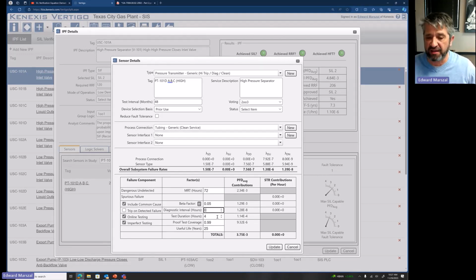So if you have a level transmitter, like a smart transmitter, it's running its program about once every 100 milliseconds to every 300 milliseconds. And so once every 300 milliseconds, it's going to run all of its diagnostic routines. So you need to basically understand for each component how the diagnostics are being performed and how frequently they are being performed. And that is going to be at the component level.